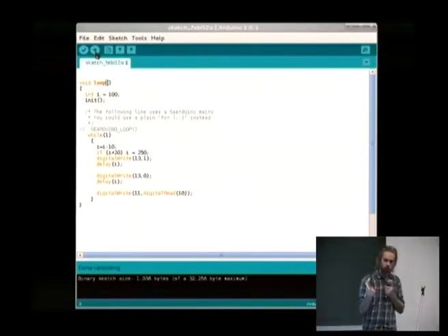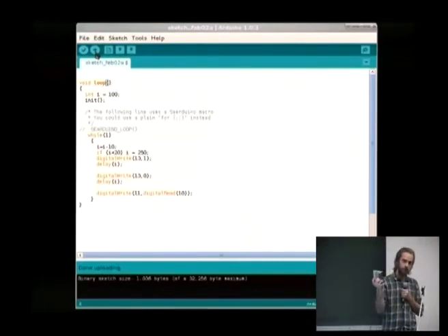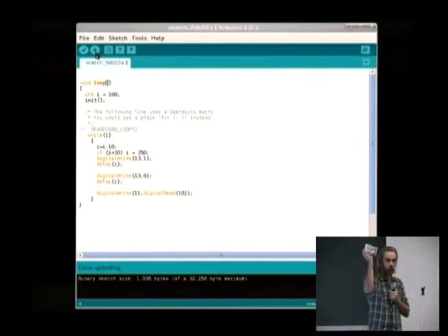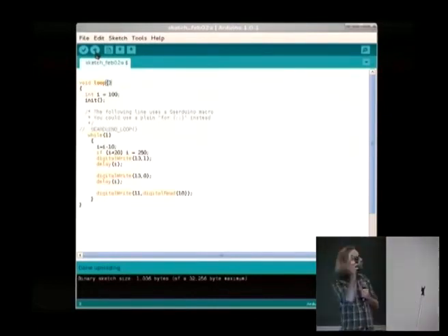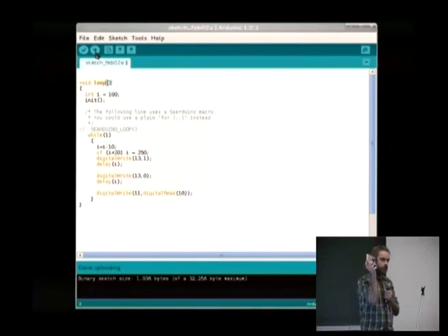A lot of times the students forgot to say what kind of pin 13 should be, or whatever pin you want to talk with. And if you don't set pin 13 to an output pin, you cannot write to it. So this code is writing to the LED, but nothing happens.